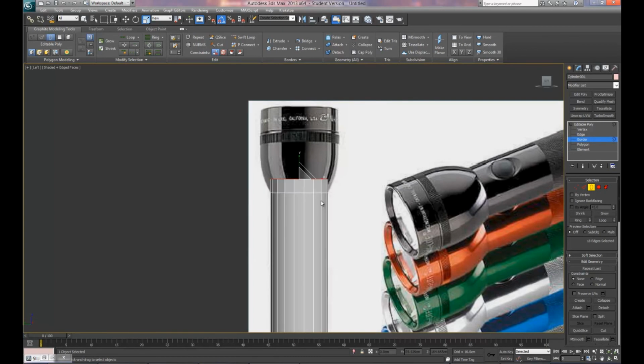So back in your left view, we're going to first, with our move tool, go up about halfway on this little curve right here, and then press R on your keyboard or click the select and uniform scale and scale it out till it's even with your reference image. Press W on your keyboard, drag it out by holding Shift. Remember, you're holding Shift and clicking and dragging, and then getting that even, and then pressing W, clicking and dragging.